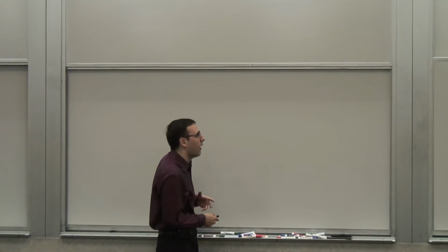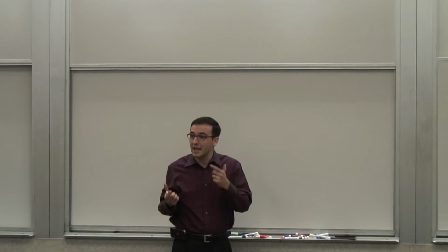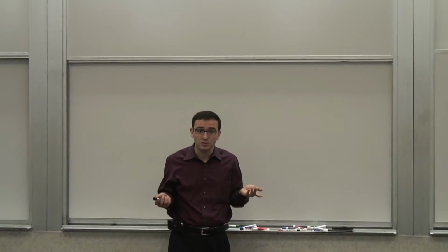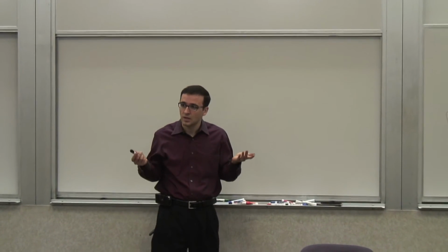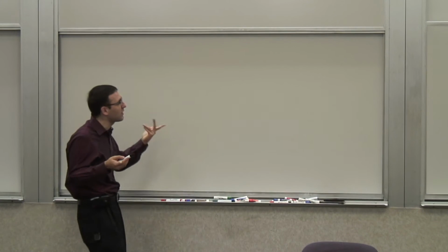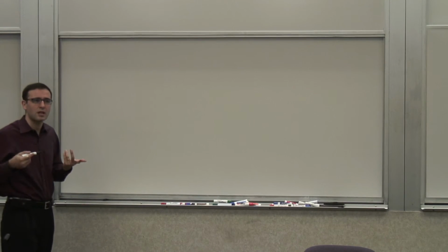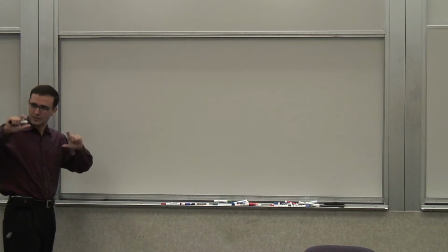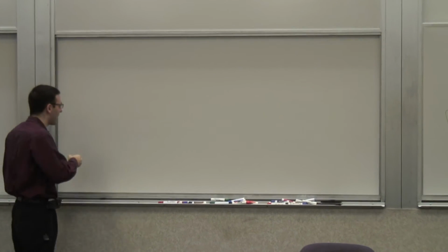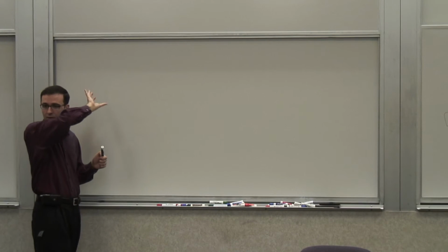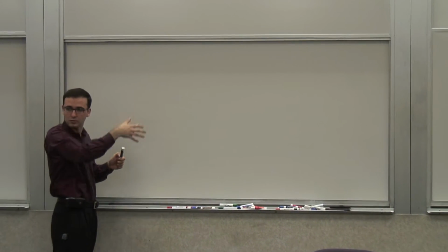So, I need a stage with differential input and single-ended output, right? And I need to see what kind of constraints I have on that in terms of performance. So the simplest stage, I know a stage that has a differential input and single-ended output, right? It's a differential pair with that current mirror up there that converts it to a single-ended output. So let's start with that.